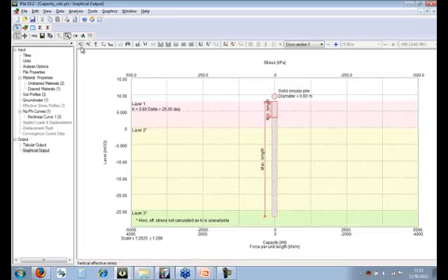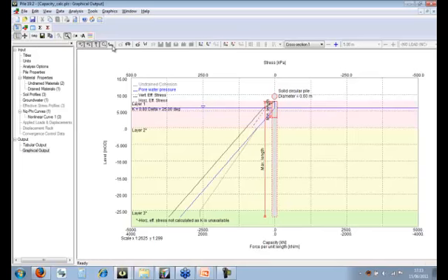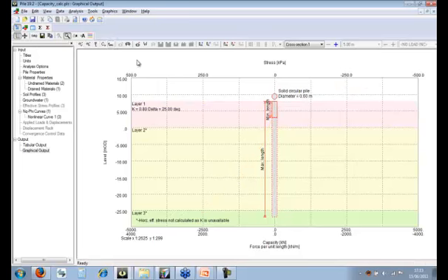But if you look at your left-hand side on Pile, these are all input parameters that I'm clicking on. So as you can see the unit shaft friction, the undrained cohesion, the pore water pressure, the vertical effective stress, and the horizontal effective stress. And this is helpful because it helps you understand your inputs and see that your inputs are as you would expect them to be. But if we go to the output, say if I had put a hollow pile in, just for interest's sake, you can actually get the plug capacity, the unplug capacity, and so on and so forth, and the internal skin friction.